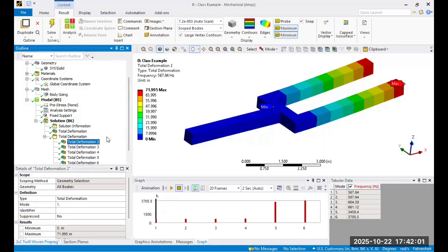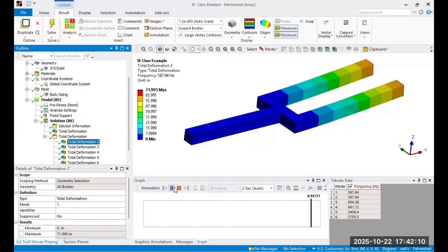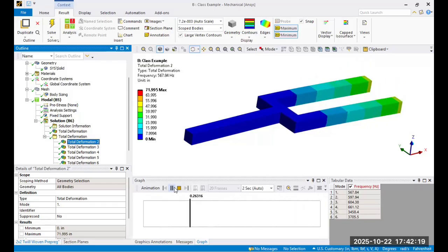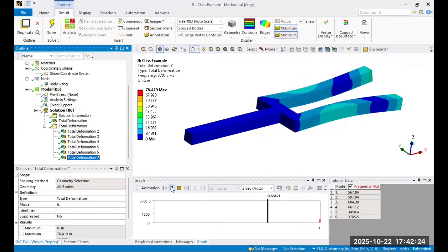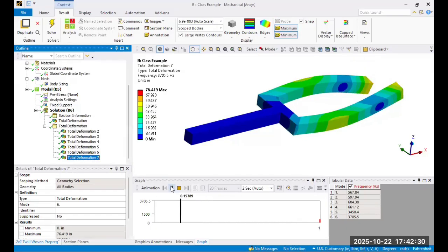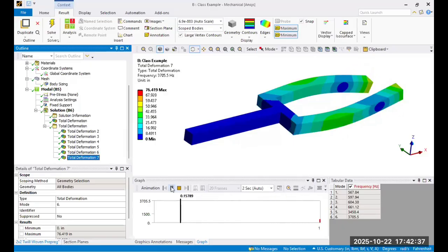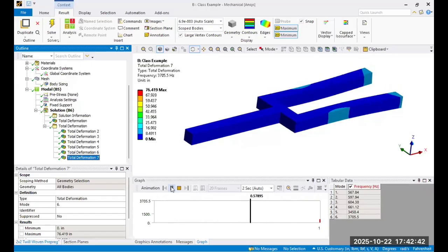For example, if you're designing an aerospace structure, obviously it has wings. If you look at the fundamental modes of the wing, you will see that it's primarily bending. In this case, it will behave like this tuning fork here. And there will be another mode called torsion that gets coupled with bending for a wing. When you have a significant amount of turbulence, that forcing function coming from the wind, the aerodynamic environment, is going to drive the motion of the wing, and amplification occurs in that wing.